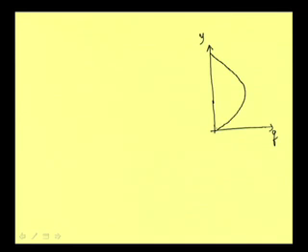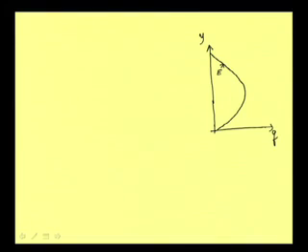It is coming like this. This is the depth discharge diagram, and this line we are getting for a particular energy level, say this is for specific energy E. Along this line our energy is remaining the same. When energy remains the same, then with the change of unit discharge, depth is changing.